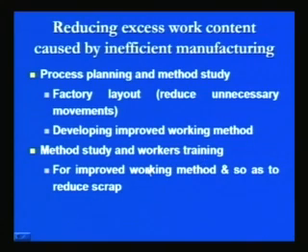Method study and the workers' training. Method study helps to develop the effective job method, which can be used for producing a given job with the minimum effort and in the minimum time. Whatever job method has been developed after the use of method study, proper training of the worker is required. So, proper training of the workers on the improved new methods helps to reduce the scrap, and so to reduce the excess work content caused by the carelessness of the workers.